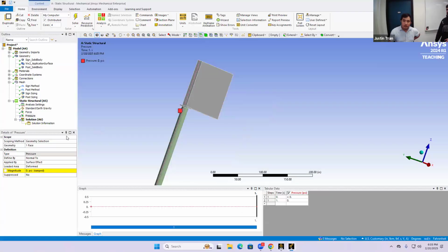Okay. So to add a spatially varying force, you basically are going to apply a function, or an Excel function, within ANSYS itself. The way to apply a function is to add an equal sign. You're going to see inside this window that says magnitude, you're going to go to tools. And the function that we're going to apply here is 0.1 multiplied by z, where z is the z coordinate of this structure.